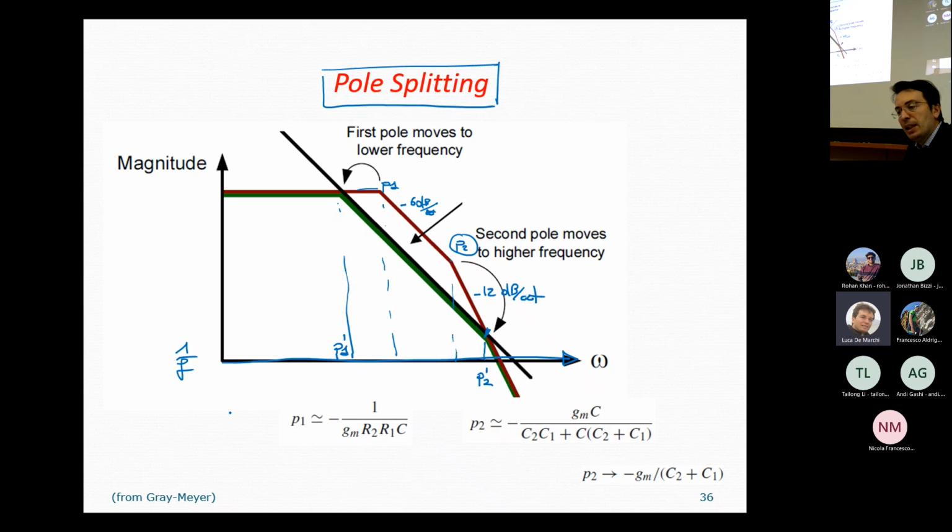So when VG2 is increased by virtue of the applied step function, we have that this current discharges the compensation capacitance here, and therefore we have a reduction of the drain voltage of transistor number 2, which means that VSG for transistor number 6 increases, and I6 as a consequence increases with a quadratic increment.